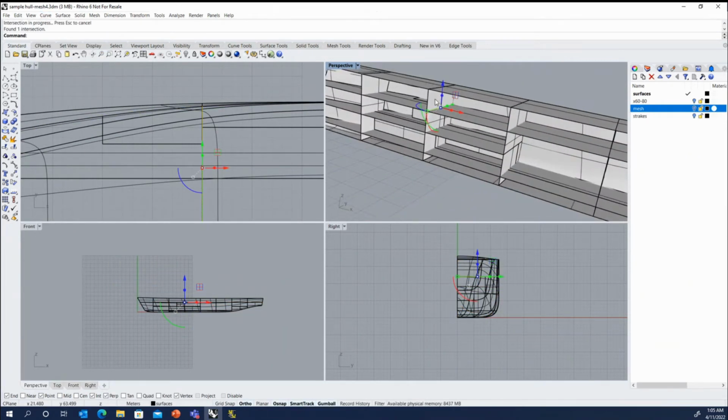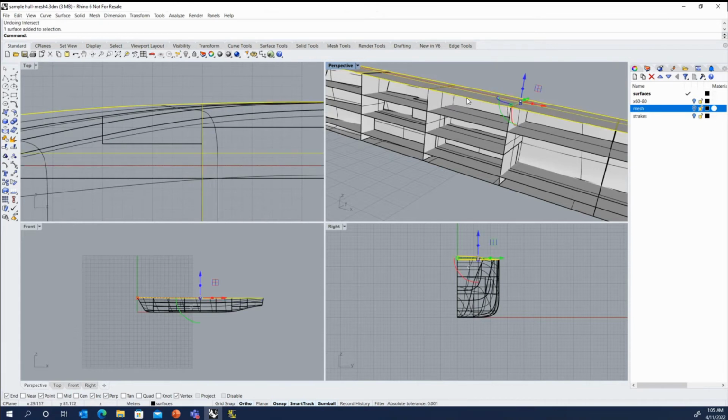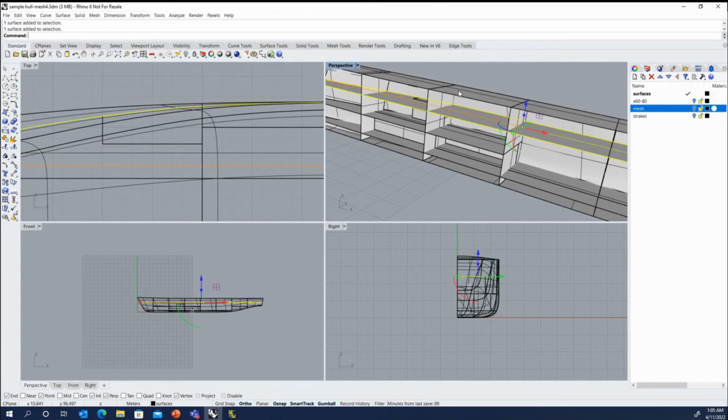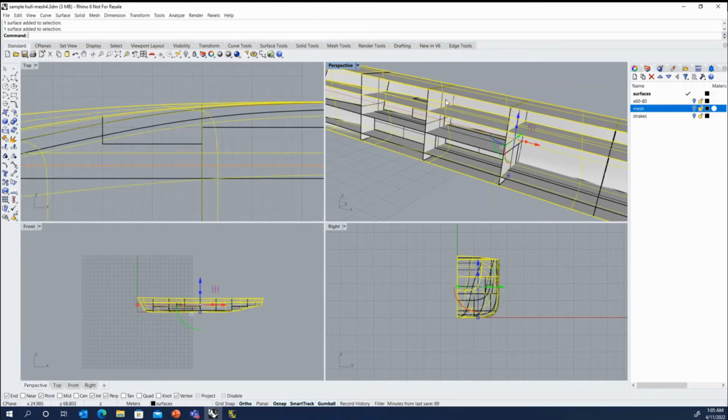So if I had this bulkhead, 2 decks, and the side shell, it would find all intersections between all of them. But a lot of times you want to intersect 2 groups of objects rather than every possible intersection. Like if I selected the deck, both decks in the bulkhead and the side shell, I might only be intending to find the curves at this transverse bulkhead.